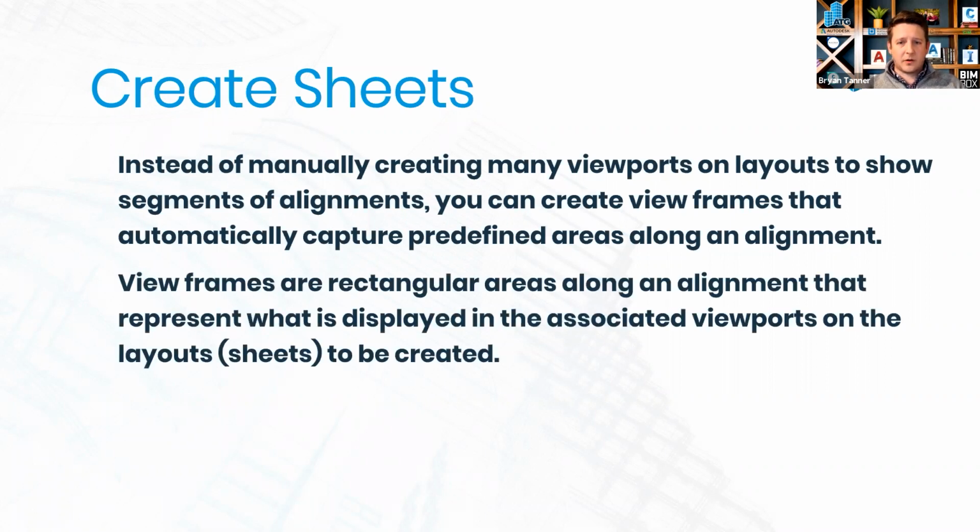The view frames are rectangular areas. It's nothing more special than that. If we have a rectangular viewport in our template drawing that we're basing these sheets to be cut from, that's the exact shape of our viewport that's going to be created in the view frames that are going to be associated to our model drawing.